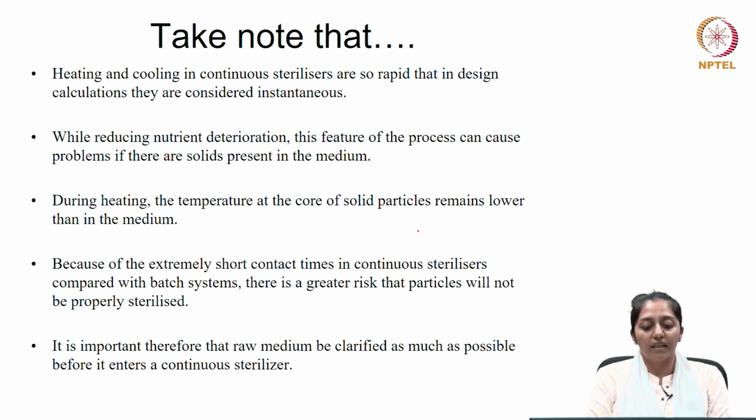Now during heating, the temperature at the core of the solid particles will remain lower than in the medium. Because of the extremely short contact times in continuous sterilizers compared with batch systems, there is a greater risk that these particles, if present, will not be properly sterilized.